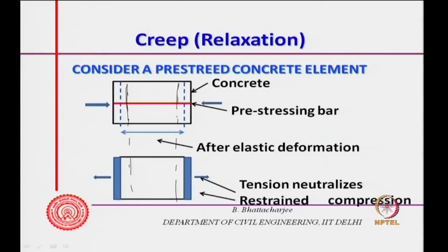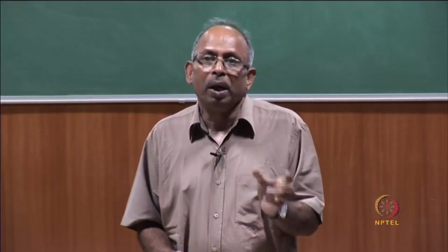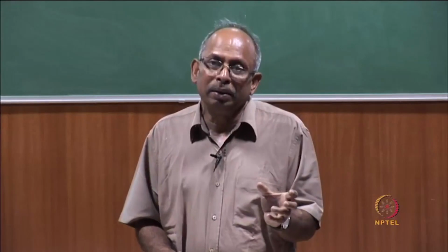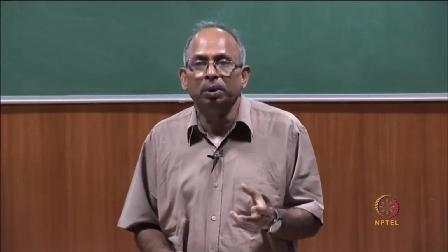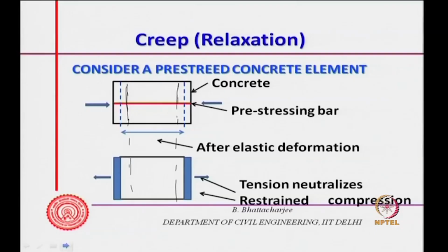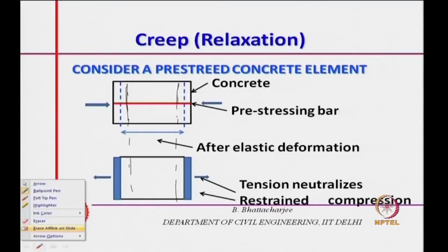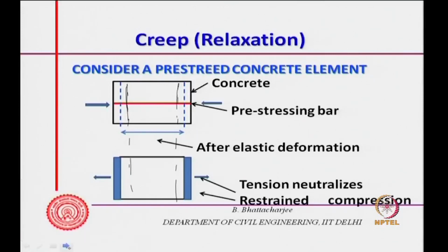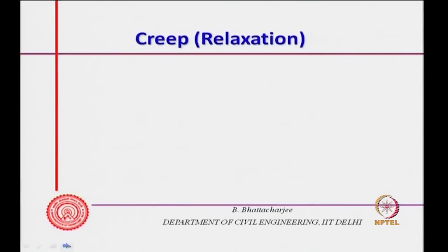This restraint means I am effectively applying a kind of tension, and this tension neutralizes the compression. So, the original compression which I have provided through pre-stressing actually gets reduced, it gets relaxed, and this is called relaxation.